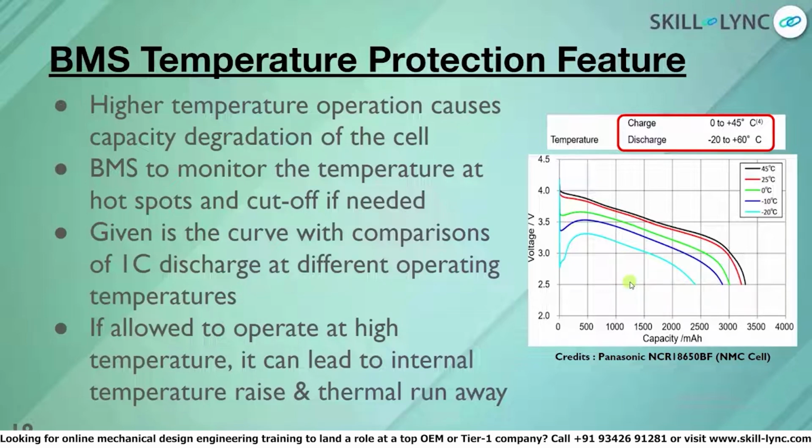Also, this is certain thing that when you overheat the cell temperature, you have a separator between anode and cathode, which we discussed in the first week. The separator is made of polymers or PP material or something, and it's of nano size. And when such amount of heat is being transferred, when the cell is being operated at such high temperatures, the separator between the cathode and anode melts. And when that melts, the whole anode and cathode are in contact with each other, which causes internal short circuit, and it can also lead to flames.